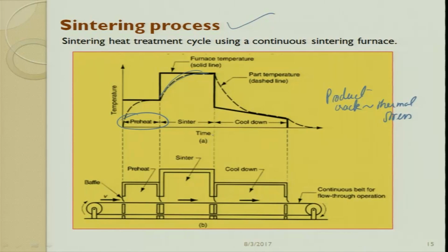This graph is very important. In any furnace, the temperature-time profile is very important. They will always ask, can you show me the temperature-time profile? If a component or a product fails, they always dig out the temperature-time profile of the heating cycle and try to figure out where the mistake was. So this is the heating cycle which is used for the sintering process,